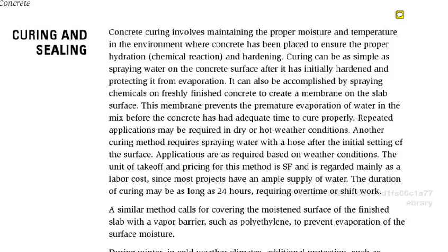Put a seal on it, and that'll keep oil or other fluids from soaking into the concrete, marring it, staining it, and in some cases deteriorating the concrete. So again, you need to read your specifications to see if you're going to be curing and sealing. You always want to cure. You may or may not seal.